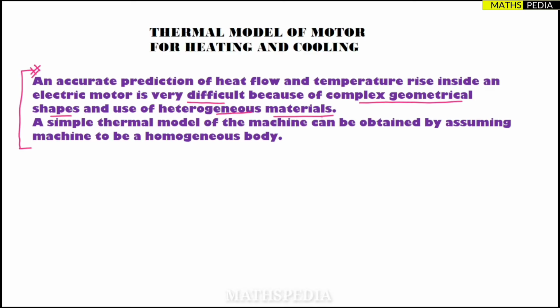So what we are going to do, we are going to consider the simple thermal model of the machine that can be obtained by assuming the machine to be a homogeneous body. Okay, we are assuming the machine to be what? Homogeneous body. So let us start the derivation. So starting with the first point of derivation, we have to write that let the machine be a homogeneous body.